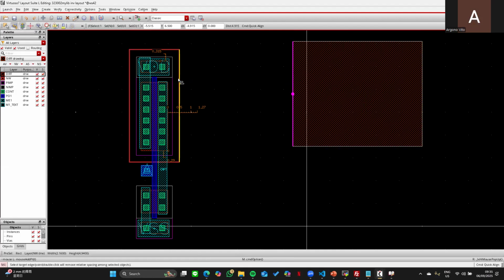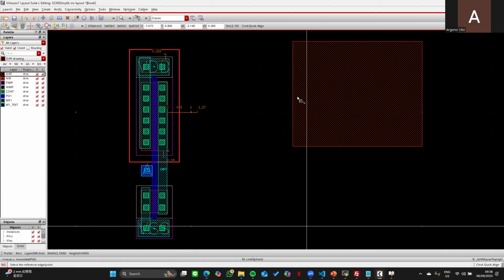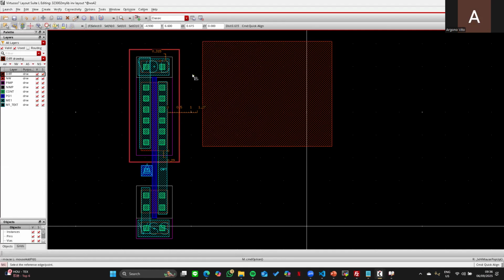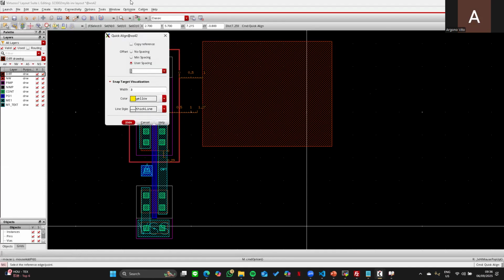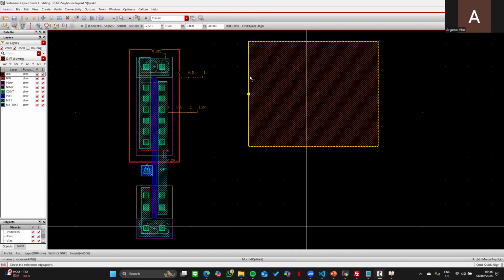You can align it, and if you use A and then F3, you can decide the spacing. So the distance in here will be one. And how do you know? You press K to call this ruler. So this is one. If we press A and F3, we change it to 3 and use K.